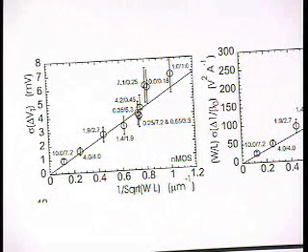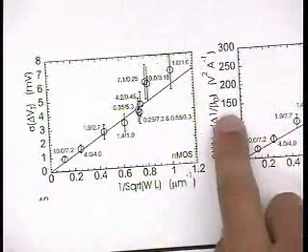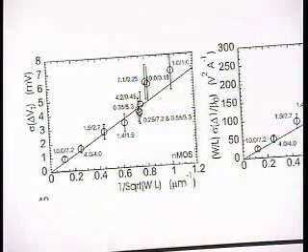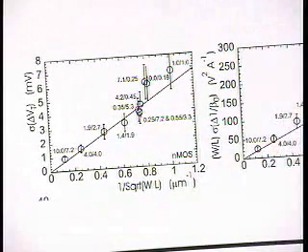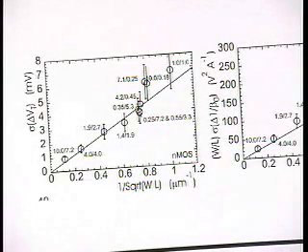So with the scaling, you said that the variations get smaller. Is that relative or absolute? Is it normalized? So for the beta, it's normalized already. For VT, it's actually absolute getting better. But your VT is also getting smaller, so at the end of the day, the normalized and the absolute are kind of tracking, right? Because the VT variation is getting smaller, but your VT is also getting smaller. Yeah.